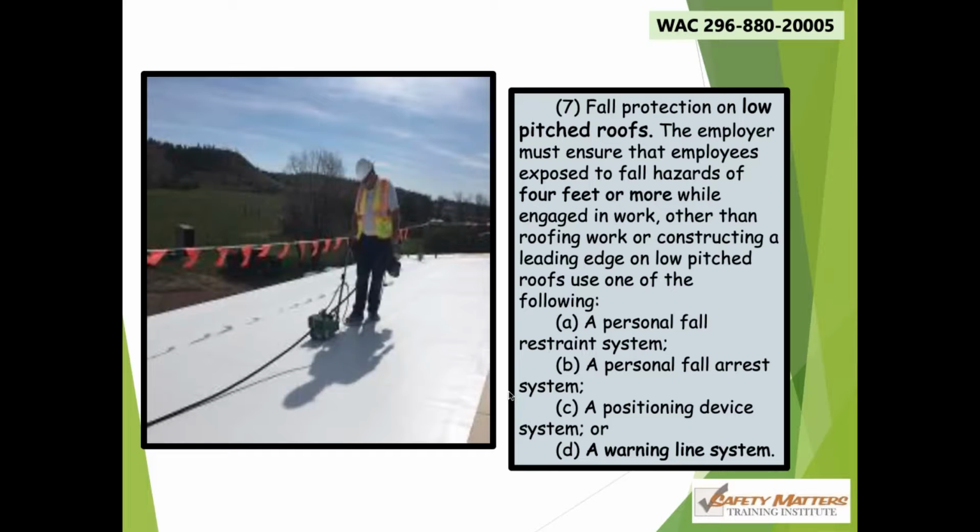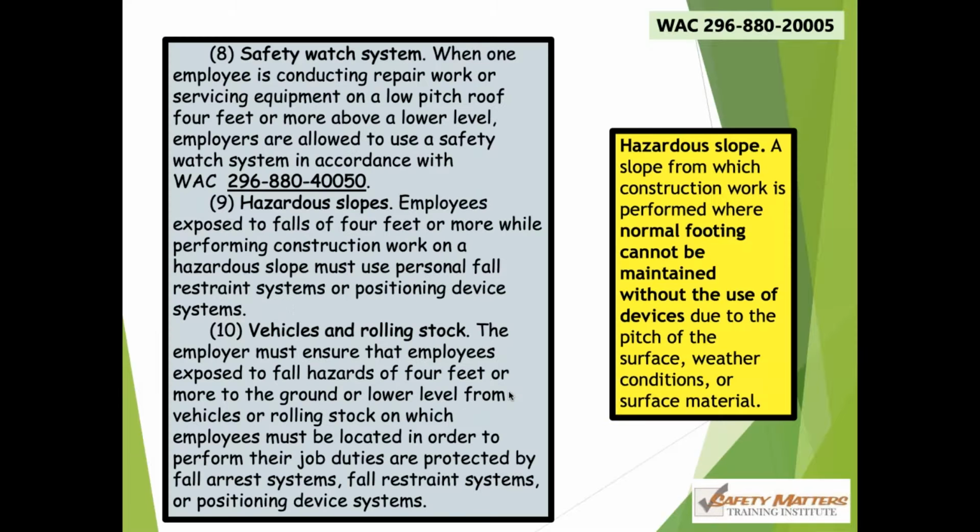On low pitched roofs, if we're doing anything other than roofing or leading edge work, if we're on a low pitched roof, less than 4 and 12, above 4 feet, we have to be protected, all right? If you're up there actively roofing, engaged in roof work, and it's over 4 feet, you don't have to protect until it gets to where? The 10-foot rule. And then above 10 feet, you have to protect.